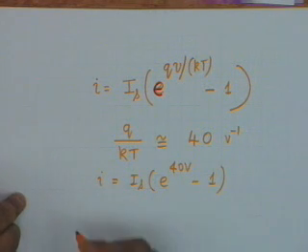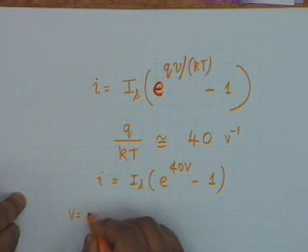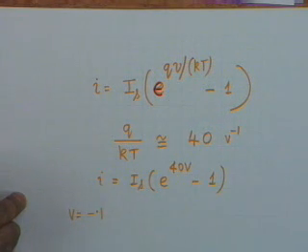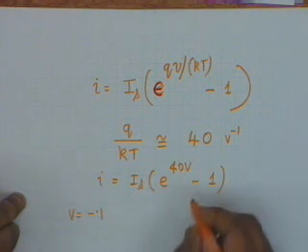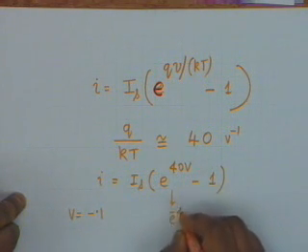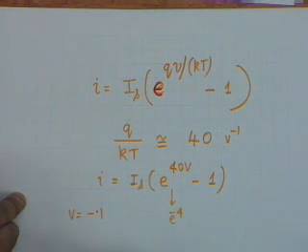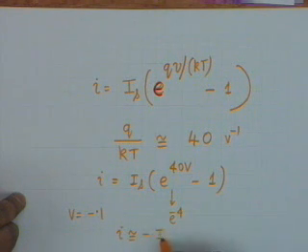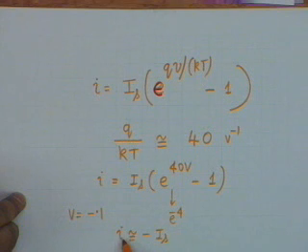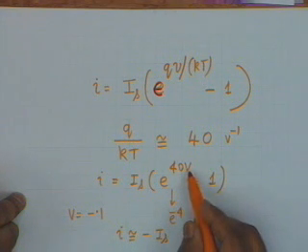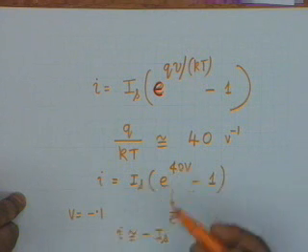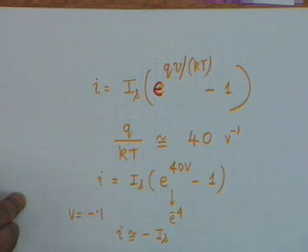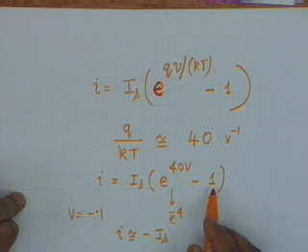And you can see that even if V is equal to, let's say, minus 0.1, reverse bias of minus 0.1 volt, then this becomes e to the power minus 4, and e to the minus 4 is approximately 0 as compared to minus 1, and therefore I would be approximately equal to minus Is. And you see how I becomes independent of the reverse voltage. Reverse voltage, if you increase it to 0.2, it doesn't make a substantial difference. From 1 you subtract 10 to the minus 6 or 10 to the minus 8, it hardly matters. So the reverse current is approximately a constant.